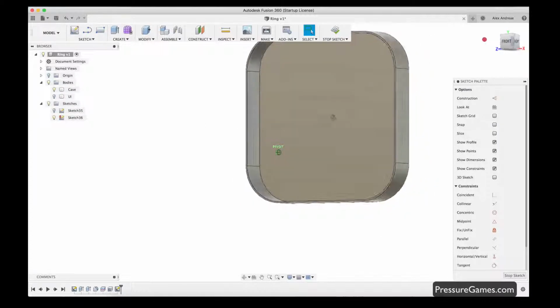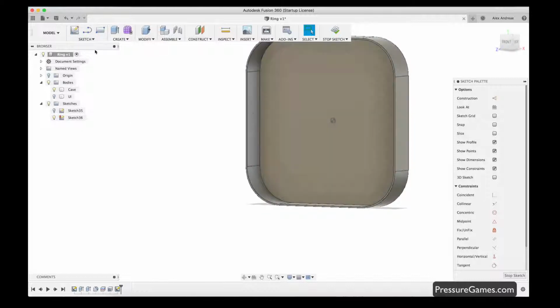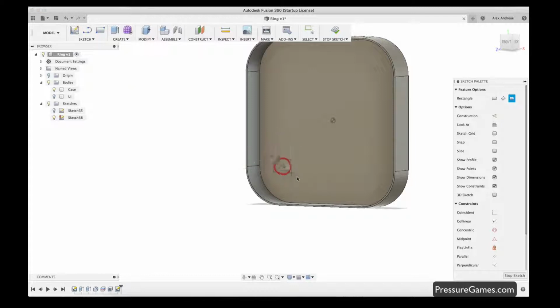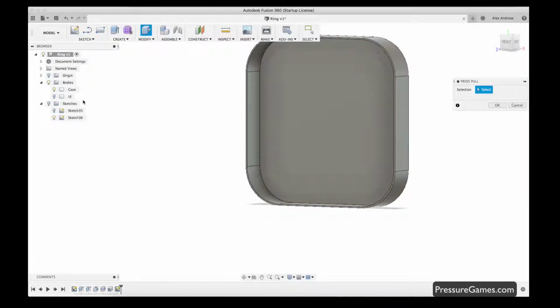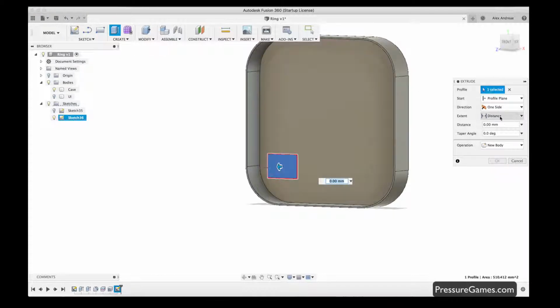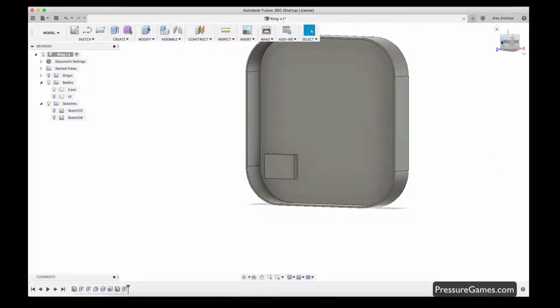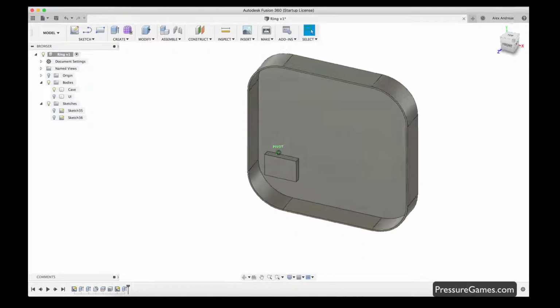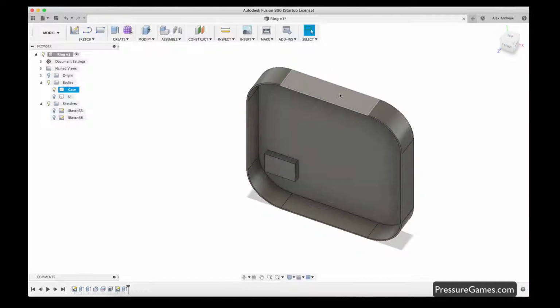do a battery compartment over here, we can really easily create another rectangle just on the back of this. I'm not going to do any real good work here, just off the cuff. We stop this, and now we want to extrude that, and we can make this 5 millimeters. So now we have some sort of case here, some sort of battery holder that would not hold any really good batteries, but you can create sketches wherever you need to add more and more elements to your design.